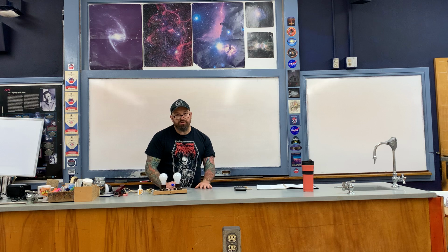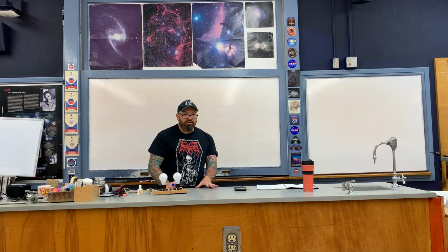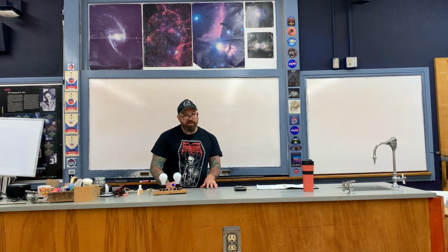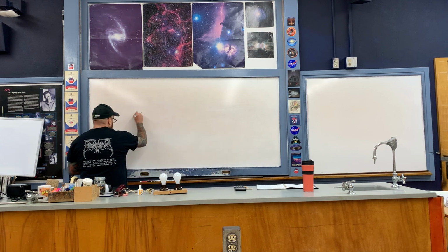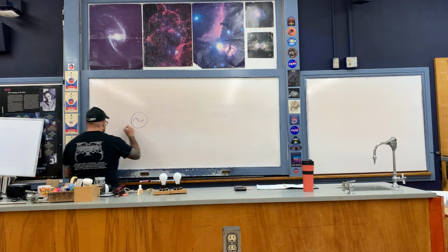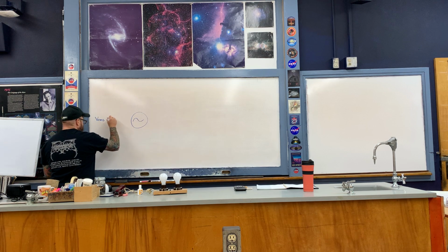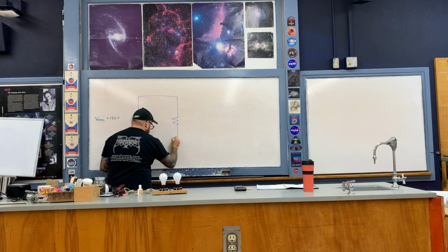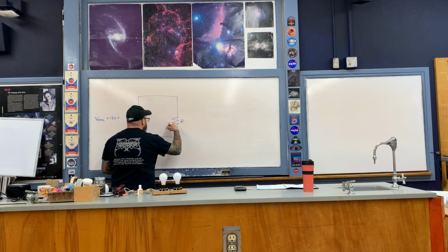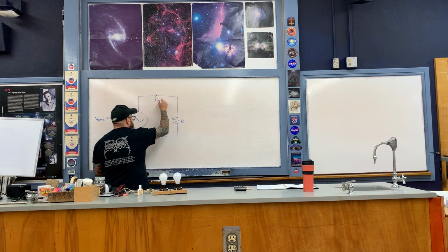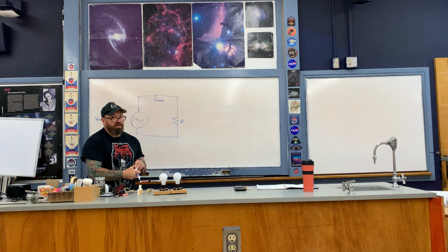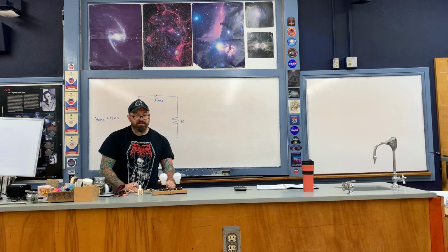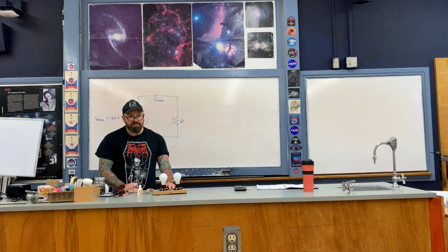So this is some of the terminology that we use here when describing alternating current. We'll just picture the hairdryer as a resistor, and therefore we have a simple diagram. Here's the generator symbol from earlier, and the RMS voltage associated with it is given as 120 volts. Then here's the hairdryer itself, which is just a resistor R. And then we have the conventional current flowing here. It's an alternating current, but we write down the average value on a simple diagram such as this. This is called the root mean square current, IRMS.